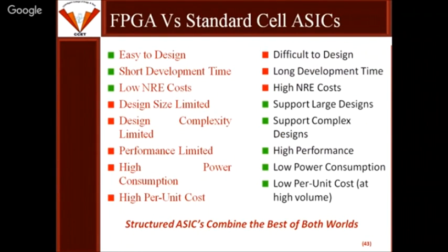So if we compare FPGA with the standard cell ASIC, FPGAs are easy to design, with short development time and low cost, while ASICs are difficult to design, with long development time and higher cost. But in other points, ASICs are much better than FPGAs, like in design size, design complexity, and performance, though with high power consumption and high per unit cost. So structured ASICs combine the best of both, and that is why we are tending towards the structured